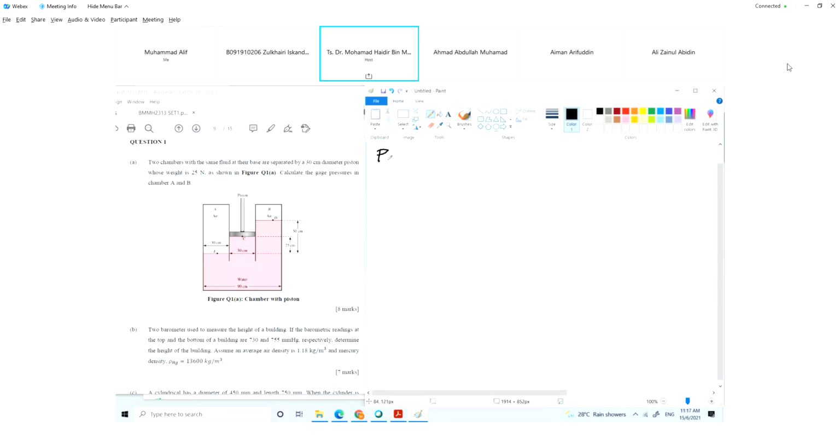Pressure at point C is equal to F over A. F is equal to 25 Newton and A is pi times the diameter, 0.3, squared over 4, so pi d square over 4. Okay, so you get the pressure at point C. Is it okay if I didn't calculate it? I just left the equation, and I leave it to you to calculate the number. Okay, so you get PC here.